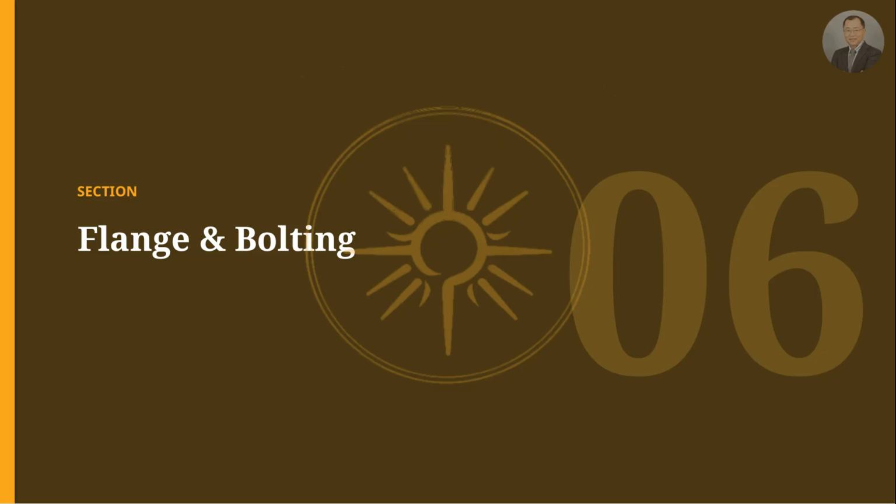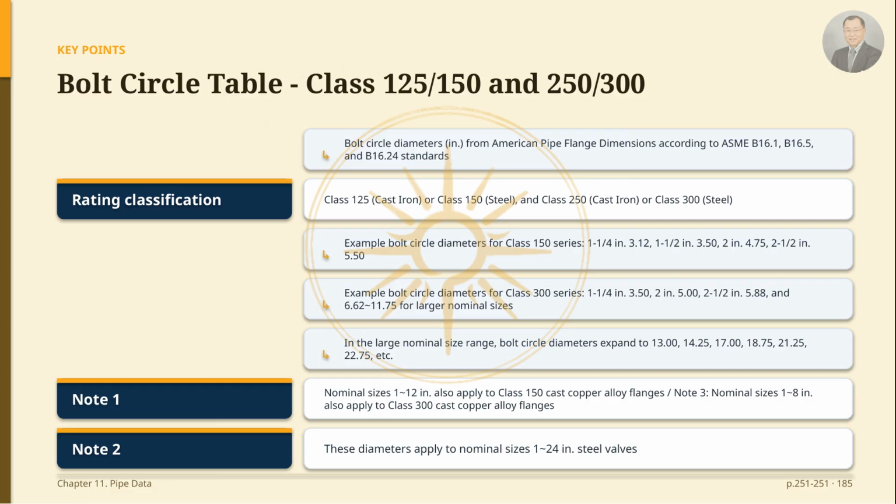Next, we turn to flange and bolting. This slide shows the bolt circle diameter table for American pipe flanges according to ASME B16.1, B16.5, and B16.24 standards. This table illustrates the diameter differences between the Class 150 and Class 300 series. For example, for a 2 inches nominal size, Class 150 is designed at 4.75 inches, and Class 300 at 5.00